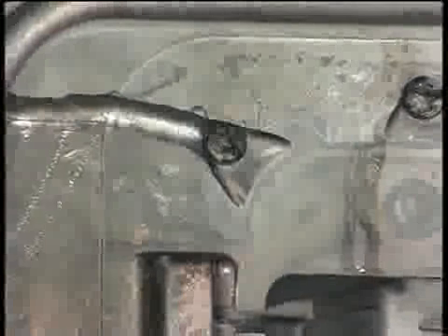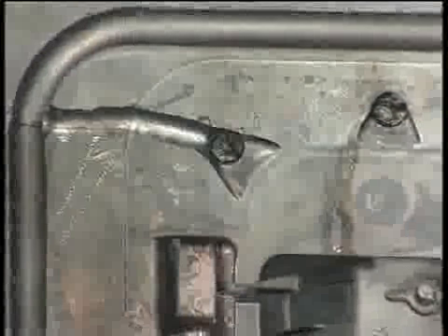To minimize porosity in the casting, the die halves have vents to release the air that is pushed ahead of the metal shot. Overflow channels in the die blocks catch surplus metal. They also assist in venting and provide locations off the casting for its ejection.